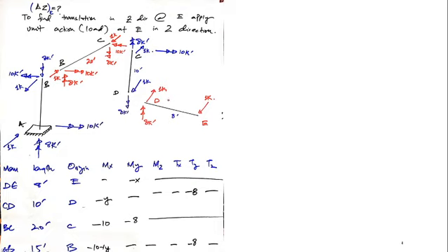Okay, next I have to calculate the del Z. I have to calculate a translation in this direction, del Z, at point E. So for that I have to apply a unit redundant action, and that should be a load. If I have to calculate theta Z at point E, I'll apply a unit moment.